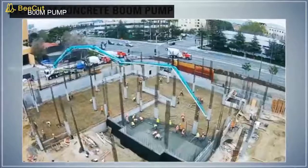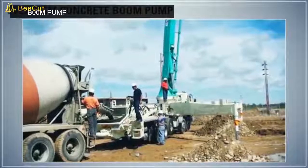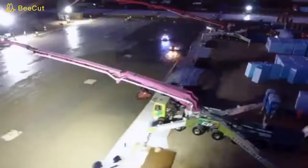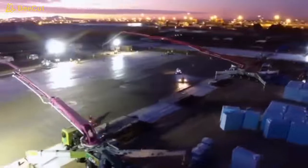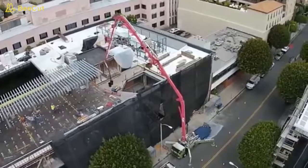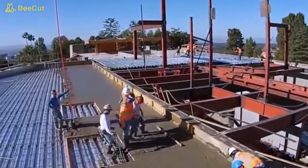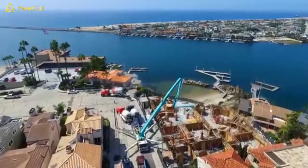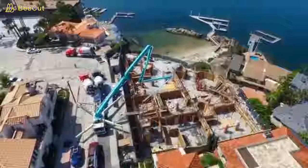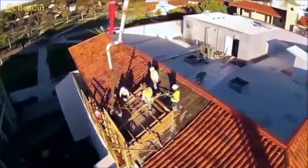For boom pumps based on support mounting, boom trucks are self-contained units consisting of a truck and frame and the pump itself. Boom trucks are used for concrete pours for everything from slabs and medium high-rise buildings to large volume commercial and industrial projects. They range from single axle truck mounted pumps used for their high maneuverability, suitability for confined areas and cost performance value, to huge 6-axle rigs used for their powerful pump and long reach on high-rise and other large-scale projects.